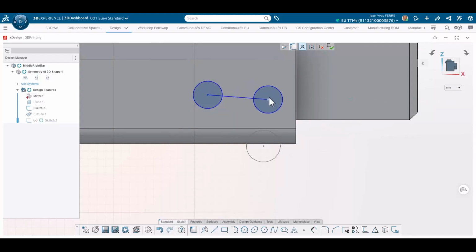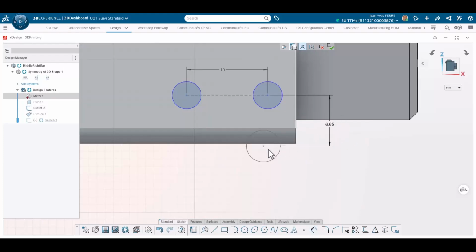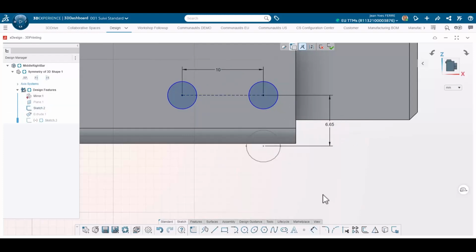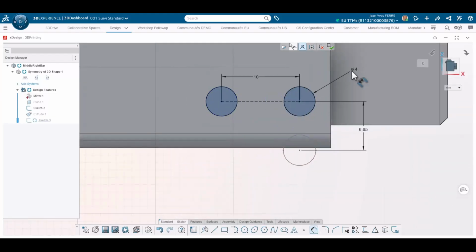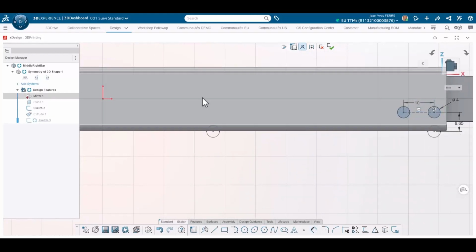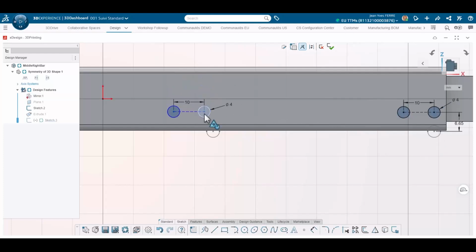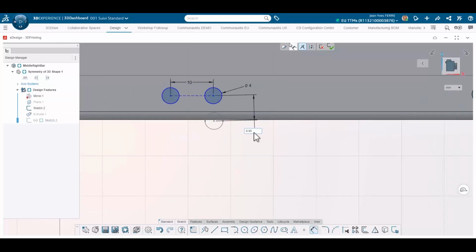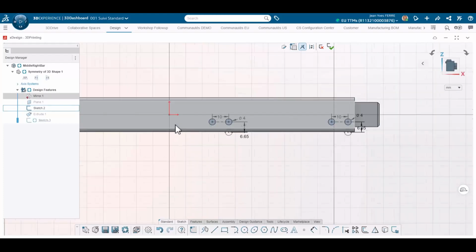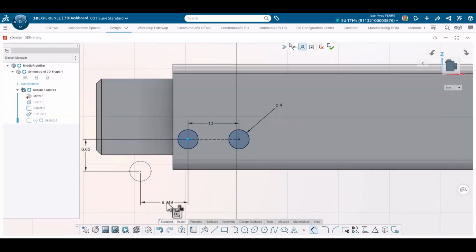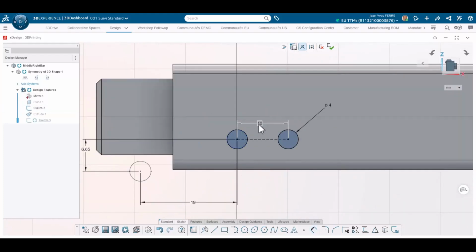Of course, this is the moment when I realize I completely forgot to drill holes in the middle bar. So I reuse part dimensions to locate holes, and I leverage all the references I have so I can place them correctly. To ease the work, I chose the same spacing for holes as when I created mounting posts. This is important to keep the same dimensions when you can. This prevents design errors you will discover when you create a physical prototype.